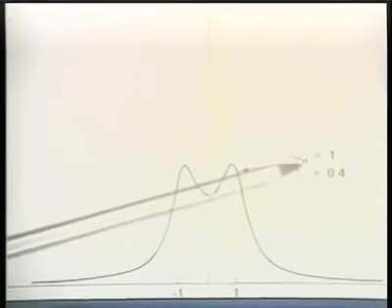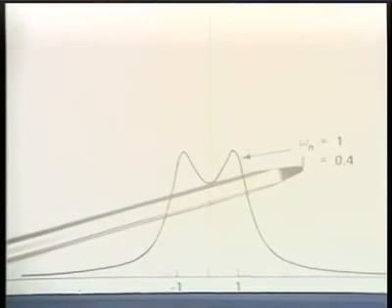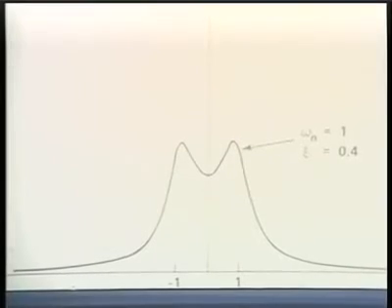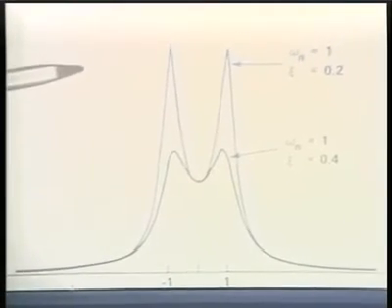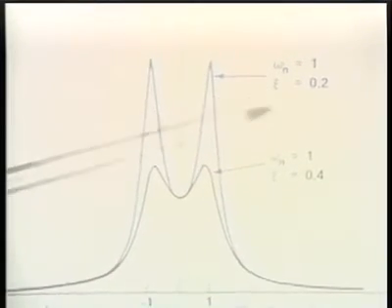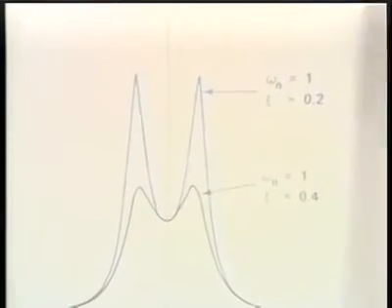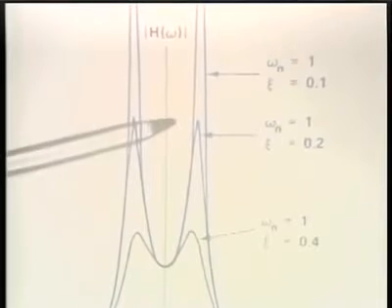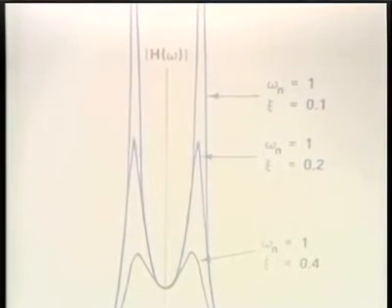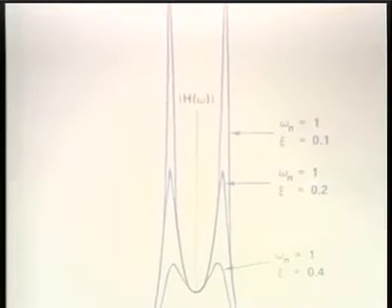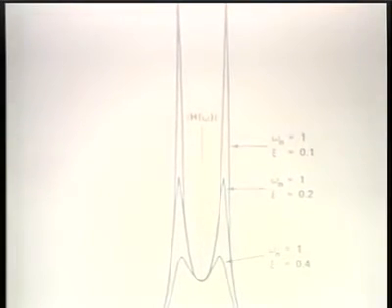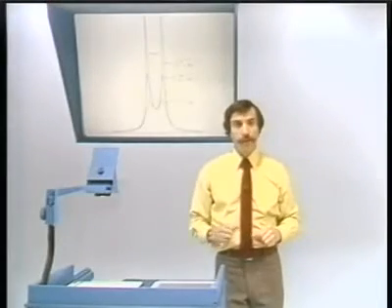This is normalized so that omega sub n is 1, with one particular choice for zeta, namely 0.4. Here is what we have with zeta smaller. And finally, here is an example where zeta has gotten even smaller than that. And what that corresponds to is the poles moving closer to the j omega axis, the corresponding frequency response getting peakier.